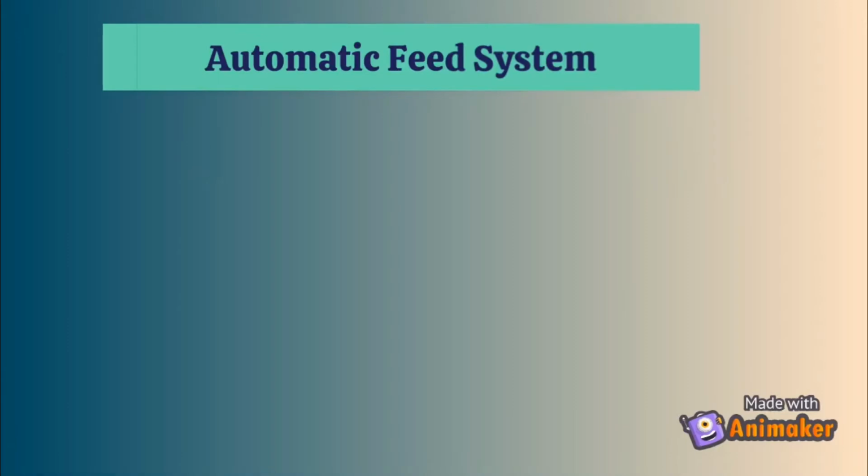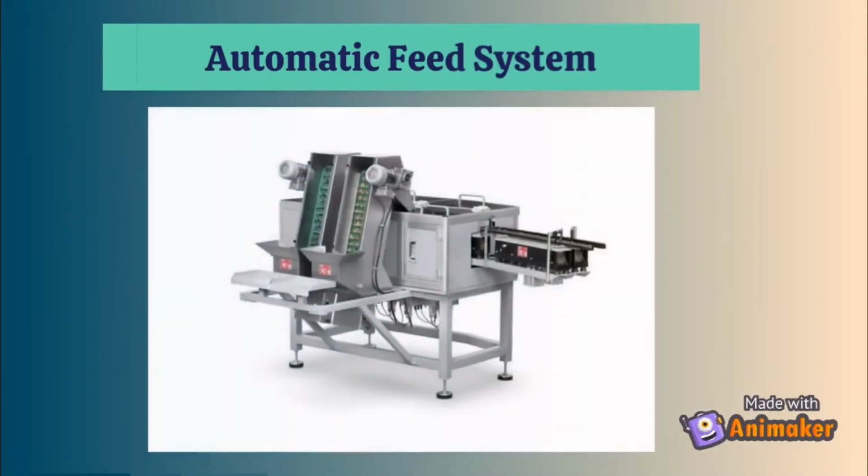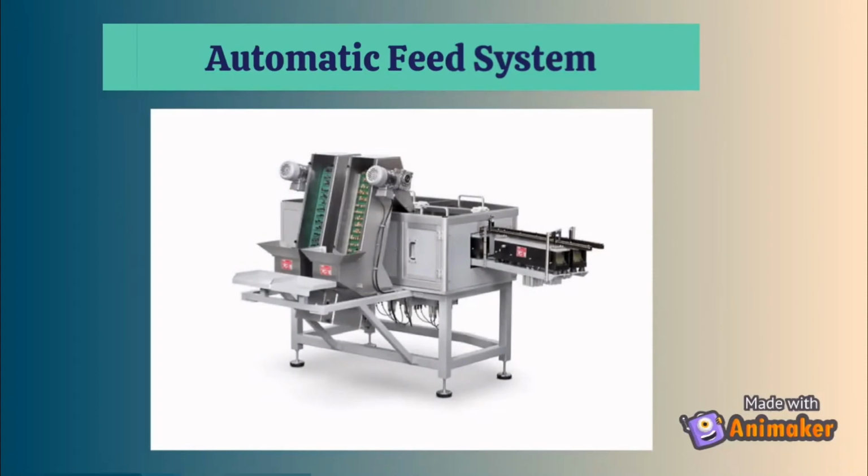Firstly, automatic feed systems feed stock to the machine from rolls. Automatic feeds eliminate the need for operators to enter the danger zone. Such systems are limited in the types and variations of stock that they can feed. They also typically require an auxiliary barrier guard and frequent maintenance.